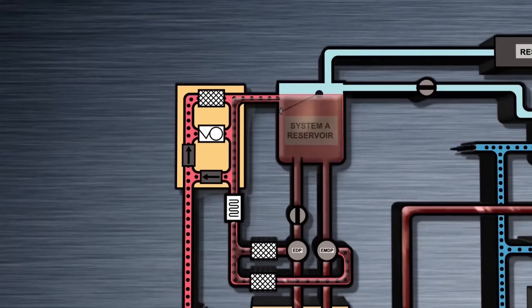Heat flows from hot to cold, so the heat exchanger transfers heat from the hot hydraulic fluid to the cold fuel in the tank. The fluid is then routed back into the reservoirs. The electric pumps generate a lot of heat and are cooled by hydraulic fluid passing through them. Because the electric pumps rely on the heat exchange process in the fuel tanks to keep cool, they should not be run on the ground if there is less than 1,675 pounds of fuel in the related tank.